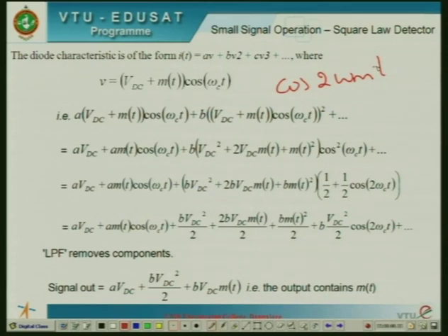The modulating signal will be translated by a frequency of 2. So this component is not required for us. Even if it doesn't have a carrier signal, because we are squaring the signal, the frequency of m(t) is translated by 2. So we don't need this component.